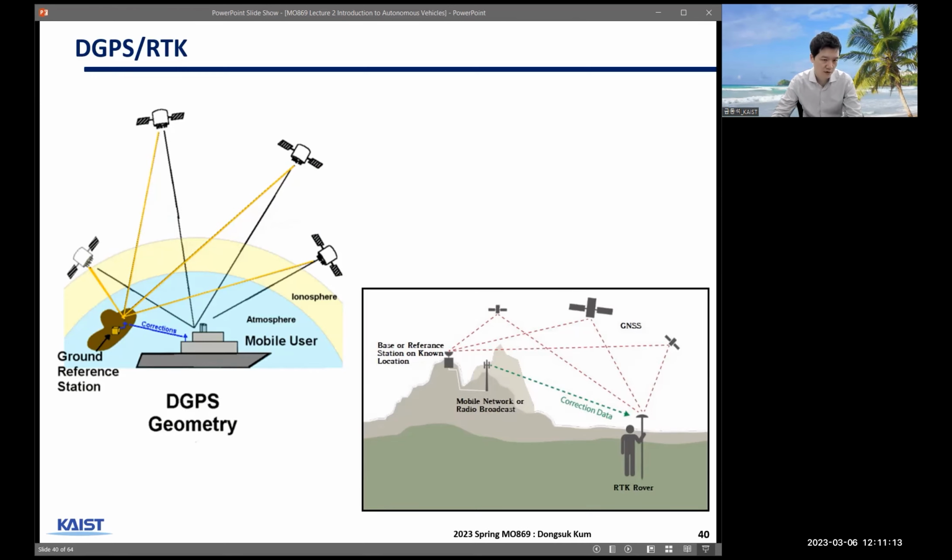We need these four satellites to compute the position of the GPS around the globe, but it may contain errors, especially when you have low cost GPS, or if you're in an urban canyon or city environment, you have a lot of obstacles, and these signals can reflect from different obstacles and can give you a wrong signal, which will give you a large position estimation error.